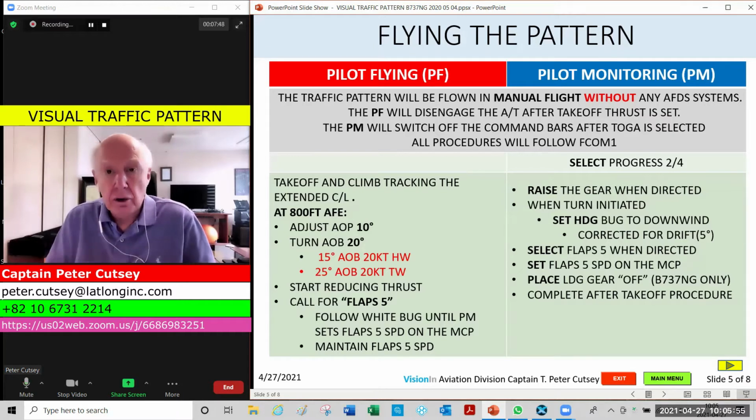A little quick formula: when you're applying wind for a crosswind at 90 degrees, 1/3 of the wind speed in the lower levels will be your actual drift. So in this particular case, if we were set, let's say, at 20 knots, that's 7 degrees of drift, and that works out fine. But today, no wind.